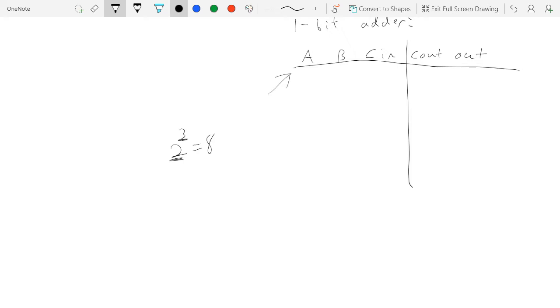So we can actually count in binary and write these out. I've got 0 0 0, 0 0 1, 0 1 0, 0 1 1, 1 0 0, 1 0 1, 1 1 0, and 1 1 1. If we count these up, I've got 8 rows here, so I've got all 8 input states covered for the combinations of A and B and carry in.